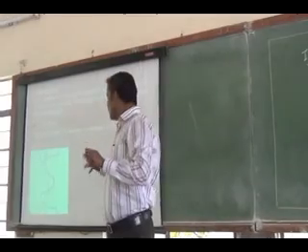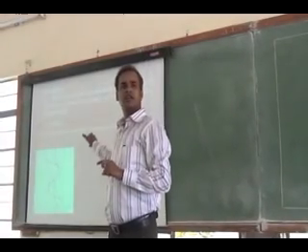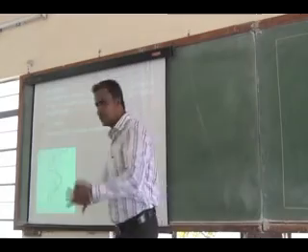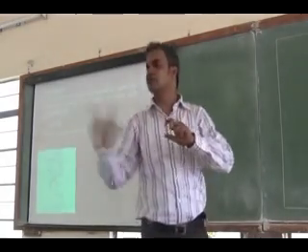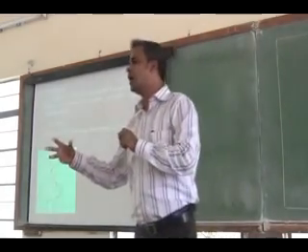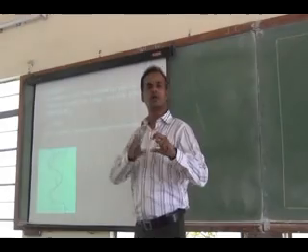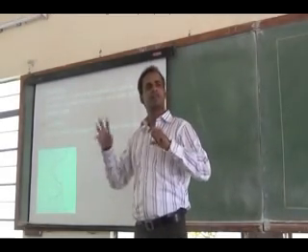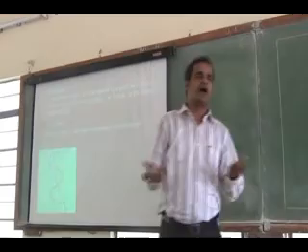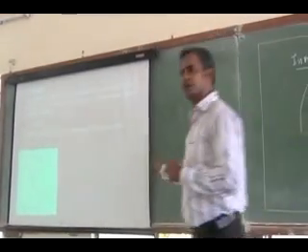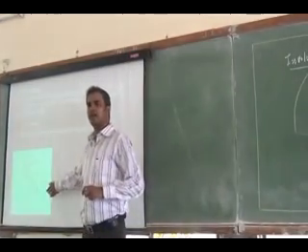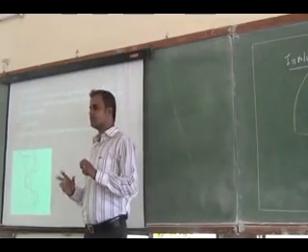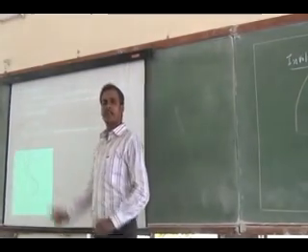If I have a gear teeth profile in the form of an involute or a cycloid, only then will a smooth velocity transmission occur from one shaft to another shaft without slipping. If the load is more on one shaft, there will be a slip in the other shaft. So if a gear has a cycloidal or involute profile, there won't be a slip and there will be a smooth transmission.